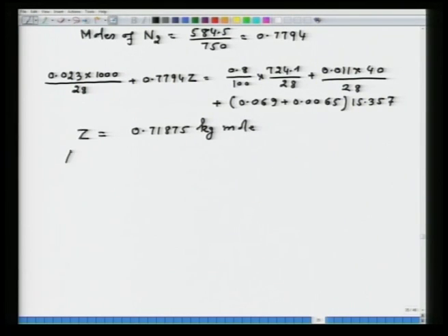So, amount of air leaked, leakage. Now, since it is kg mole, I can express it in meter cube when I specify the temperature and pressure. So, amount of air leakage is equal to 20.84 kg mole. You have to multiply by its molecular weight, or if you want to find out in meter cube, you multiply by 22.4, at 1 atmosphere and 273 Kelvin. Or you can also find out at 750 millimeter and 26 degrees Celsius as the temperature is given in the problem, but then you have to find out 1 kg mole corresponding to meter cube at this temperature and pressure. Anyway, you can find out the way.